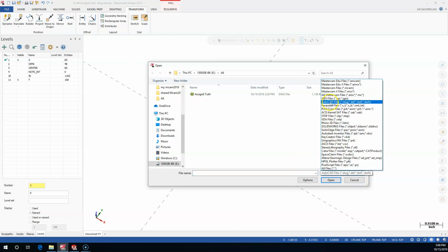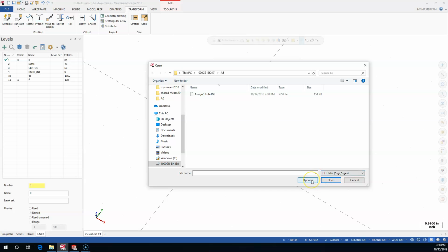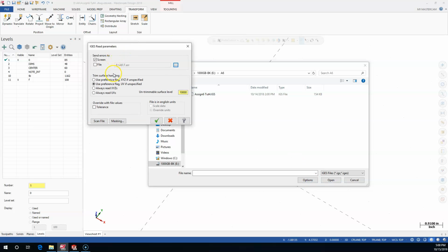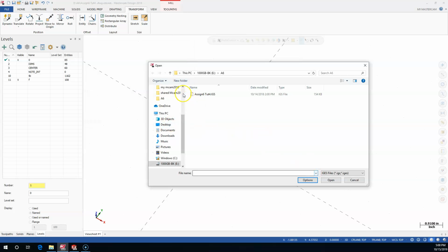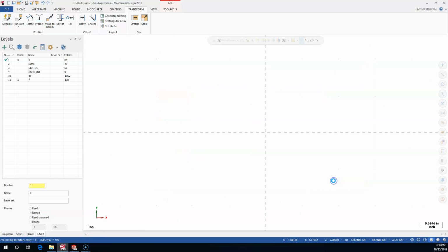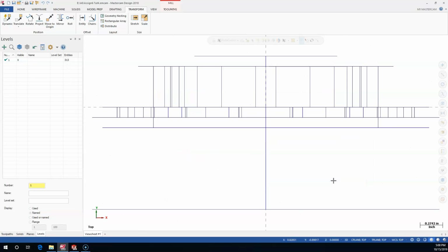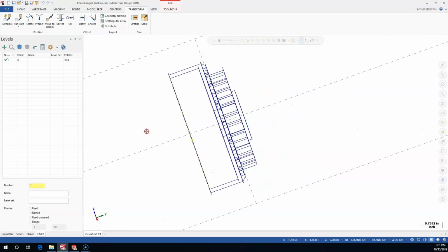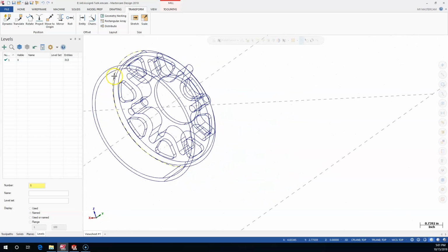We also have an IGES file, and IGES is probably the older International Graphics Exchange. It's been around forever, and it comes in with a lot of stuff. So again, with the trimming, orientation, I believe I set this to just do curves. If we went in through the DWG model, the problem with the wireframe is that it's going to flip-flop and do some strange things as we're rotating. But this gives us all of our geometry in straight wireframe.